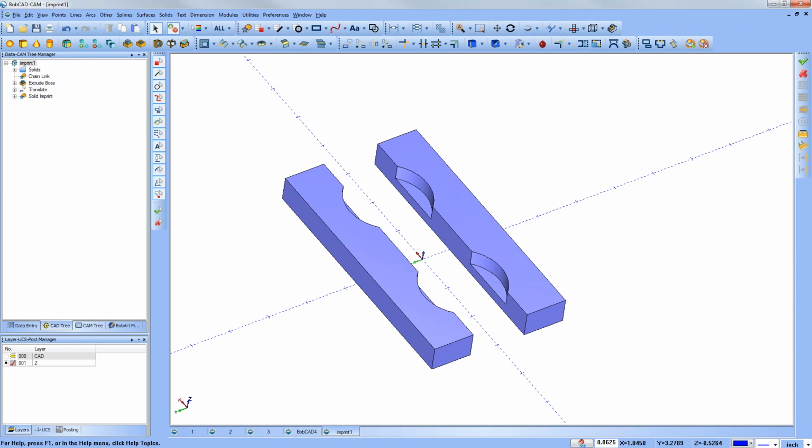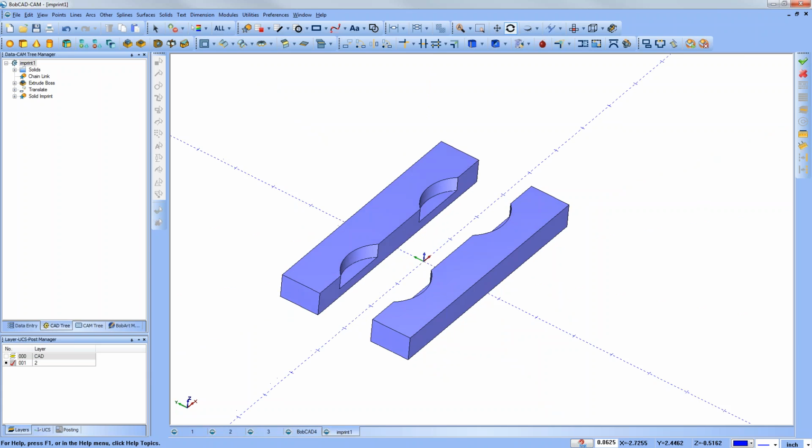So normally what you had to do in the past, like I mentioned earlier, is extrude a solid, then take the other solid, maybe do a Boolean subtract. Well, one of them goes away, right? The one that you're not leaving. So then we'd be left with this shape, but your original would be gone. In this case, it does all those steps in one,